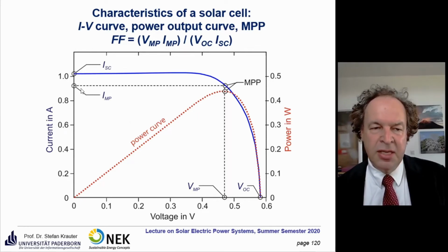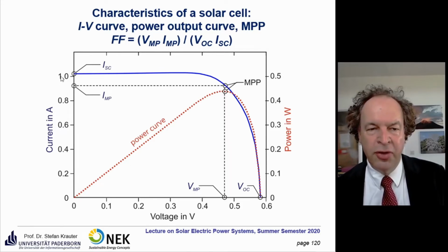perspective. So we have here the short circuit current, the open circuit voltage here, and here we have the power curve. First, at the highest current, at the short circuit current, we have the lowest voltage, it's exactly 0. So power output is 0 at that point.